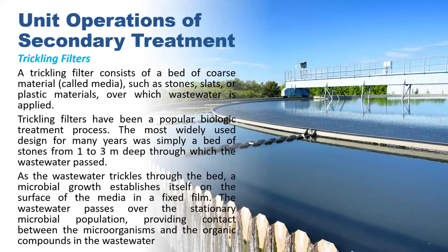The most widely used, designed for many years, was simply a bed of stones from 1 to 3 meters deep through which the wastewater passed. As the wastewater trickles through the bed, a microbial growth establishes itself on the surface of the media in a fixed film. The wastewater passes over the stationary microbial population, providing contact between the microorganisms and the organic compounds in